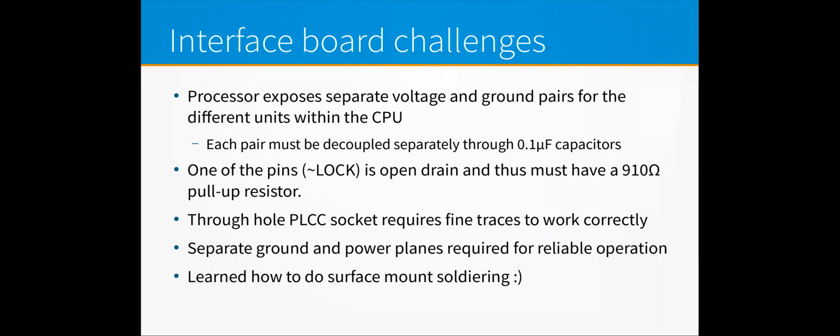And then on the underside it would be ground. Not only does it make it less likely to burn, it also distributes any sort of current across the entire area, so it'll cool much faster, in a better way. The only downside is that if you have a lot of traces, you may have to get really creative and use vias to worm your way across the board to have consistency.